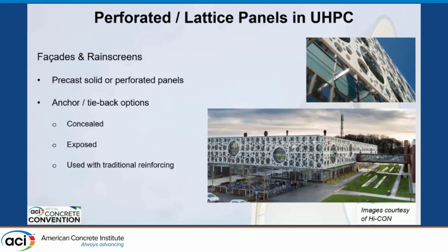You can also, of course, design it so that there's a large section of voids. This is over 65% voids in these rain screens, these panels. They have concealed tiebacks. You can see here up in the upper right, they've got these standoff connections to the wall. These are cantilevered out, and because you have these large voids, you don't have as much weight, so you're able to design for that.